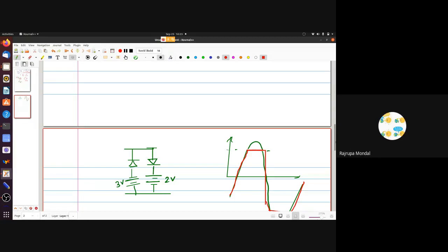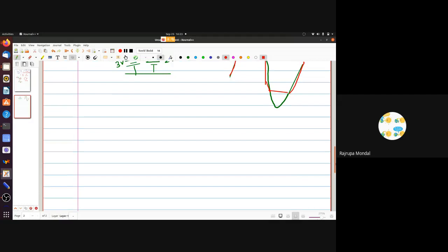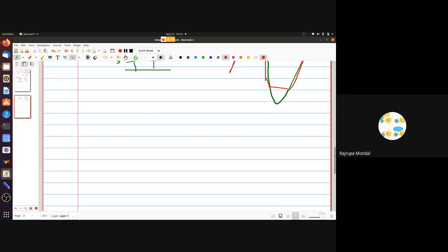So when you calculated the ripple factor during the starting of the video, you considered that the capacitor discharges at a constant rate, right? Yeah, V_p by R. So from that, when we are considering that the output is constant, how can we calculate the change from something which is... So that of course is an approximation.